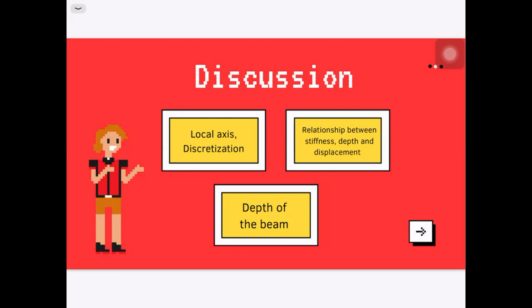The usable area is increased when we use the appropriate or minimum depth. However, it should not be less than 0.35 meters of depth because the beam will not be able to resist the moment and leads to a longer beam, which is unsuitable as it has large deflection.